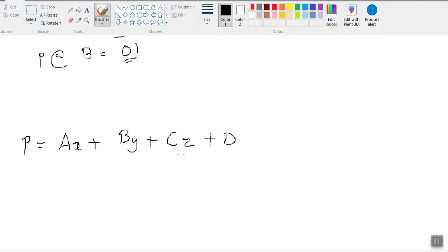These are the actual values. If you want to convert this non-uniform into uniform, you can give the coefficients A, B, and C as 0. So this pressure will act as a uniform distributed load, as in the case of a slab. Okay, this is the actual kilonewton per meter square.